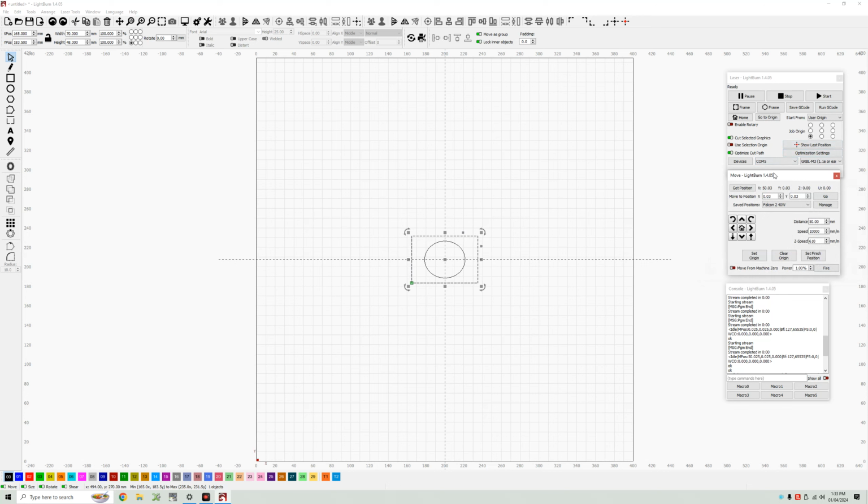you can send it to go, so it's going to move over there. And like I said, it records where the thing actually is when I hit set origin. You got to make sure it's where you want it. And I hit set origin. It wrote it right down here somewhere. Yeah, 0.025, 0.025. They only give you 3 decimal points. My much more expensive CNC goes out to 1/10,000. But then again, there's a $28,000 price cap.